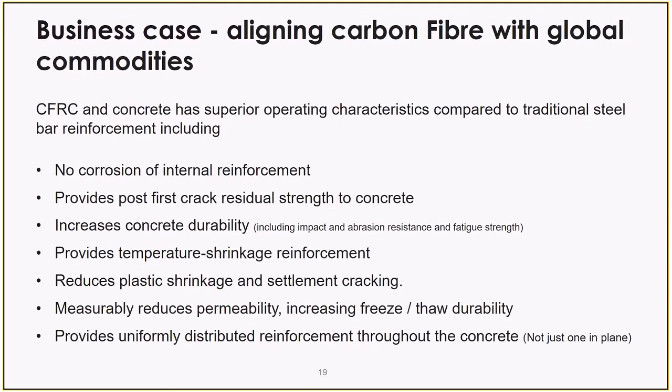This is, generally speaking, as this is emerging, it has superior operating characteristics to traditional steel reinforcement bar. And I'm just going to cover a few of these. No corrosion of internal reinforcement. It doesn't corrode, so you can imagine that has significant advantages. Post-crack residual strength to concrete, concrete durability, shrinkage reinforcement. These are major issues for the concrete industry globally with steel. So you can see there's some tremendous advantages of carbon fiber in concrete. So that's just one area.